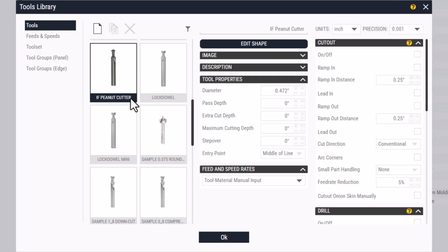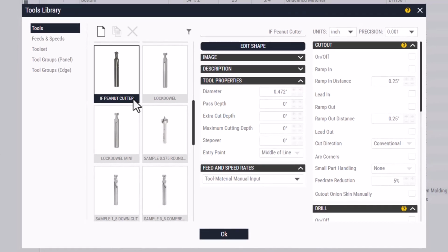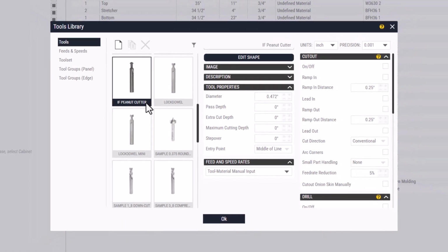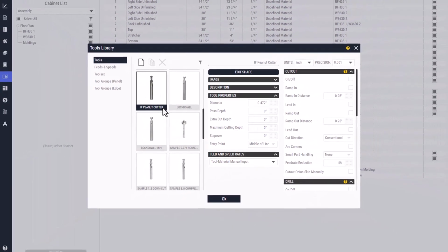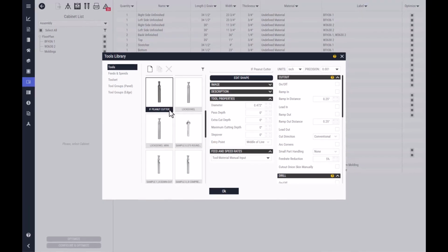Intelligent Fixings lists 14,000 RPM as the recommended maximum for CNC use. Treat this as a maximum, not as a universal feed and speed setting. Use feed and plunge values that have been verified for the physical cutter, CNC machine, and material being processed.